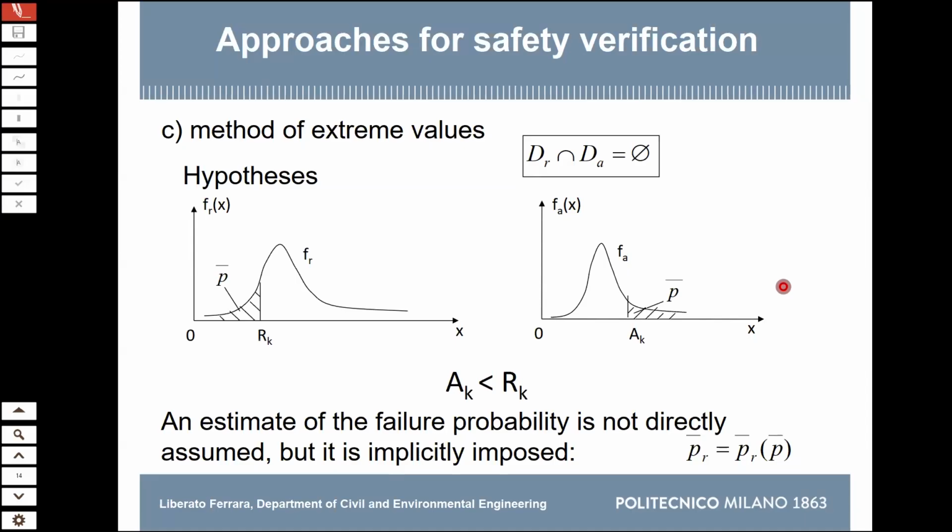In most cases, we don't know the distribution, but we accept that value to be the upper 5% percentile. Well, what does it mean? It means that we are selecting for our design calculations a value which is sufficiently high, not the highest possible, because mathematically speaking, this has no limit. So we have to accept, at a certain point, to make a cutoff.